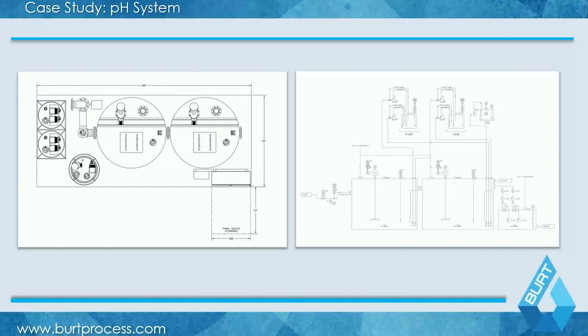And it is worth noting you always have to have an effluent monitor for any pH system. It's typically gravity. And people also have lift stations on the effluent of a pH system as well, if you have to pump up into your drain, as opposed to being able to go strictly by gravity in those cases. And you always have to measure pH as part of your effluent. You may have to measure flow. You may have to measure more such as temperature as well, depending upon what your permit is and also what you're dumping down the drain in those cases.